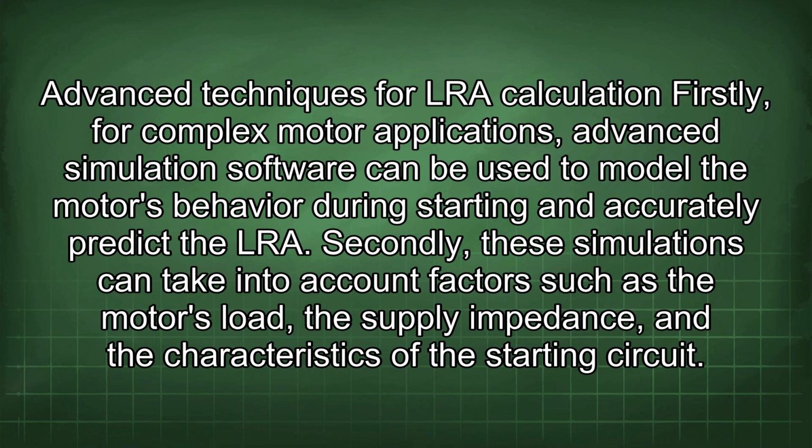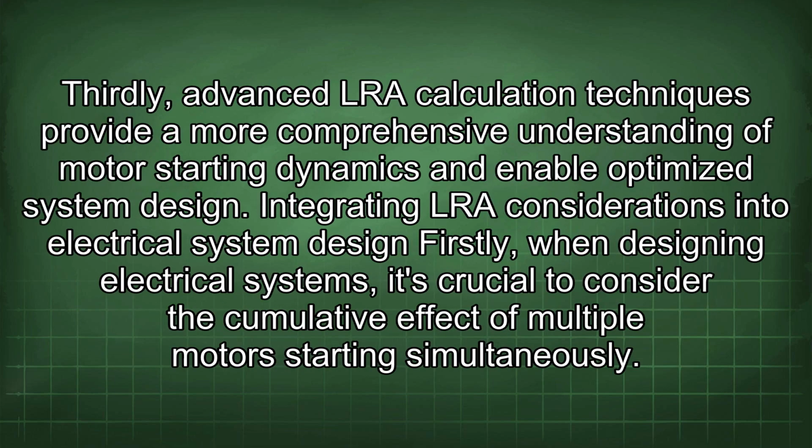Advanced techniques for LRA calculation. Firstly, for complex motor applications, advanced simulation software can be used to model the motor's behavior during starting and accurately predict the LRA. Secondly, these simulations can take into account factors such as the motor's load, the supply impedance, and the characteristics of the starting circuit. Thirdly, advanced LRA calculation techniques provide a more comprehensive understanding of motor starting dynamics and enable optimized system design.